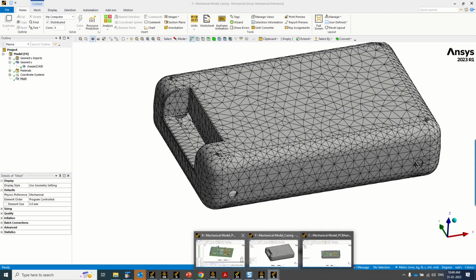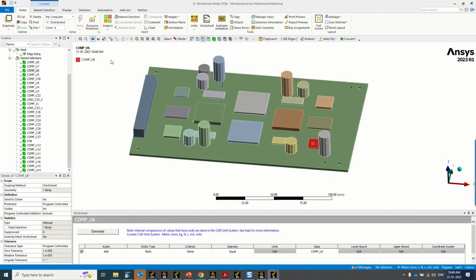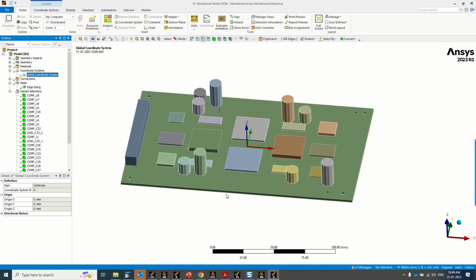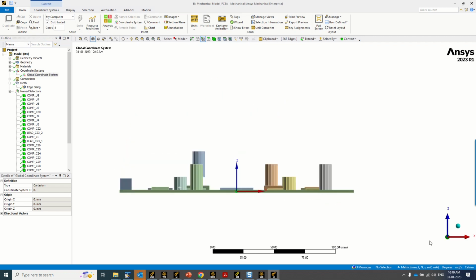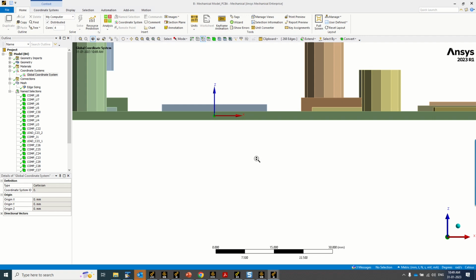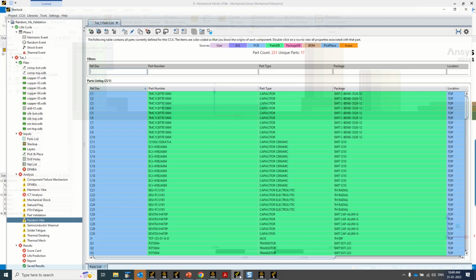You do not move the location of the PCBA, because when we are importing the results back into Sherlock for post processing, it will look for its orientation. The PCB is identified based on the orientation that we define in Sherlock.